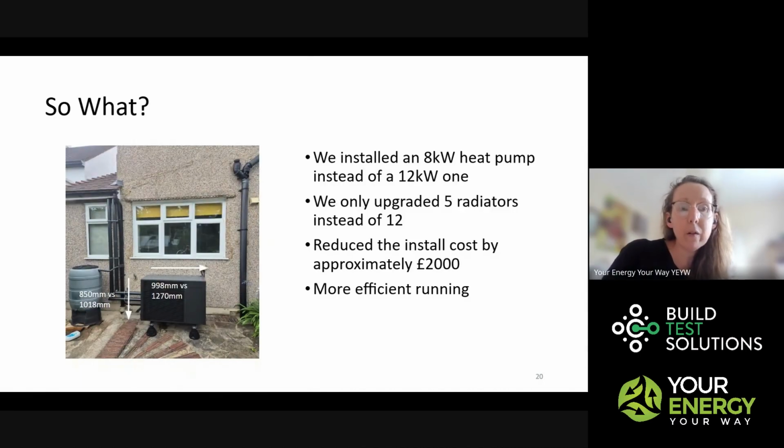So on the next slide, it's just kind of a so what. I've just put the different sizes of the two heat pumps onto this. So the customers, although it does look like they've got quite a lot of space out the back there, this is their seating area. They were quite concerned about having a really large unit. So this unit is just under 1 meter rather than 1.2 meters, and height-wise only 85 centimeters rather than a meter tall. So some reduction in size, which is a consideration for customers.